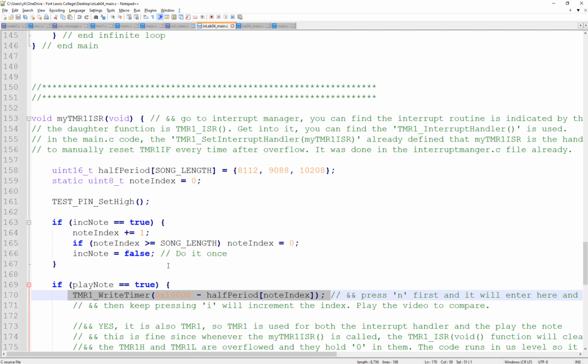So every 4.1 milliseconds, it triggers this, okay? It's going to run the top part really quickly. So what's happening is it triggers the interrupt, comes to the timer, and starts writing that starting value into the timer register. That takes a while to run. However, it's conflicting with the interrupt, right? What's happening?